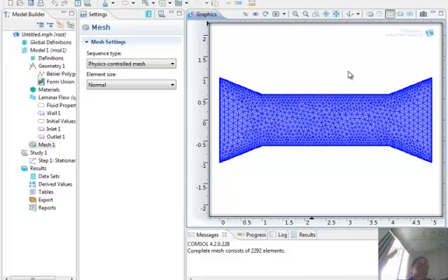So because we are approximating the differential equations by algebraic equations, derivatives by their approximations, the derivatives have to be evaluated accurately. So you need mesh points that are close to each other. And this is why when you select physics controlled, when it knows a boundary is there, a wall is there, it puts more points near the wall. Okay, and you can play with this.